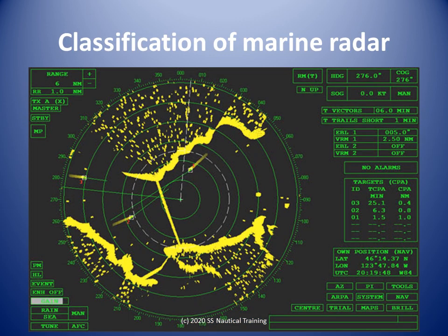The marine radar is classified under the X-band, 10 GHz, or S-band, 3 GHz, frequencies. The X-band, being of higher frequency, is used for a sharper image and better resolution, whereas the S-band is used especially when in rain or fog as well as for identification and tracking.